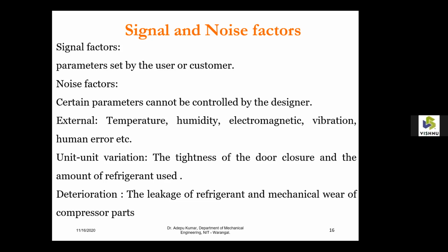Then electromagnetic fields are also there. Suppose electromagnetic fields surround your welding process, they deflect the arc due to the magnetic field. So you are not getting the correct temperature or correct energy at the particular area where you are going to weld. That leads to incomplete depth of the melting area, and that leads to defects in the weldments.